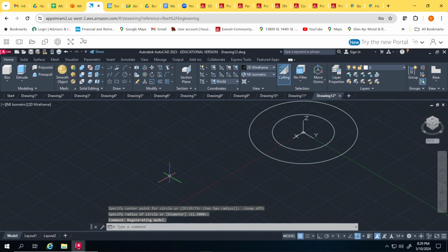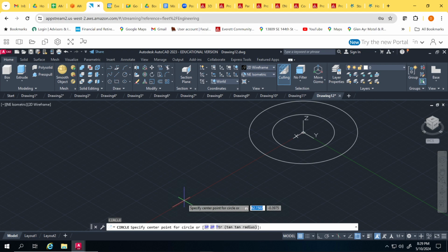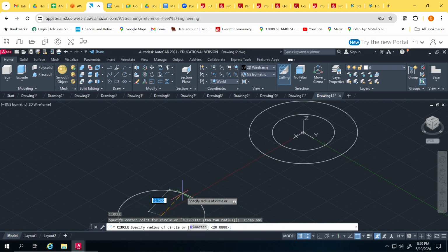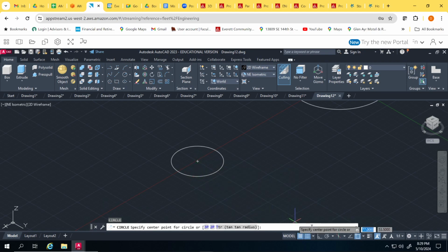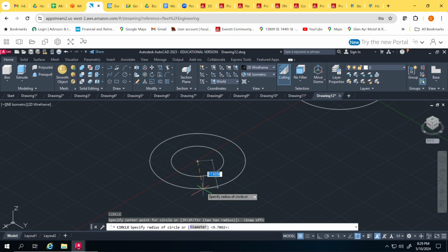And we'll do 2 more circles. So I'll hit enter to create another circle. And I'll just put it right about, I'll turn the grid back on. I'll put it right about here, let's say. And I'll slide out. It'll be a little smaller on this end. So I'll hit enter, turn the snap to grid off, go to the edge of that circle, snap it so they're concentric and come out like so.